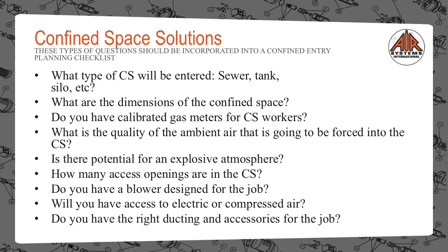I know we have covered a lot of information and some of it's new to you. To summarize, these questions will help guide you in getting started making a confined space entry checklist. What type of confined space will be entered? Is it a sewer, a tank, a silo? What are the dimensions of that confined space area? Do you have calibrated gas meters for the confined space workers?